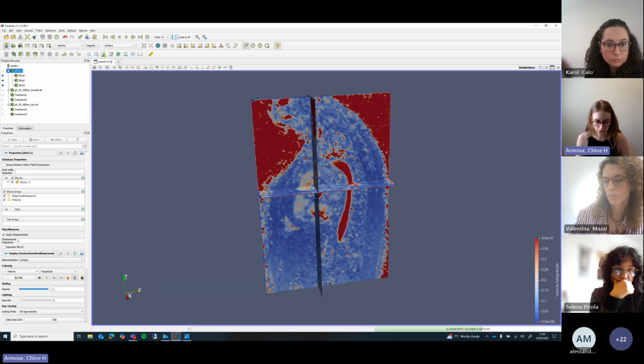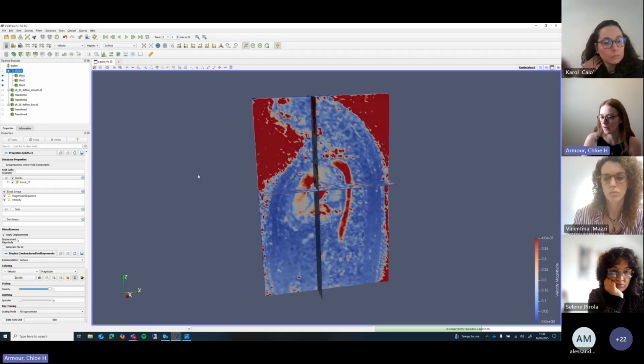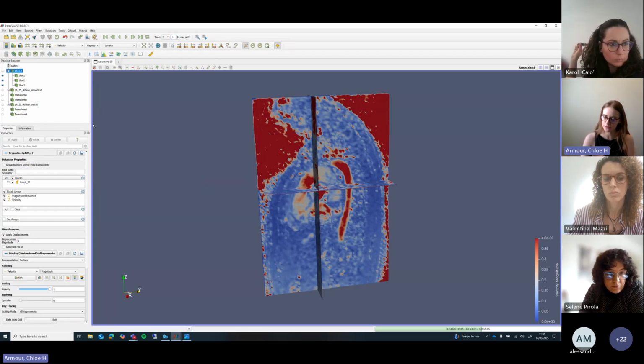25, 30 time points is quite a good resolution. You don't get too much more than that usually, due to the limit of the patient being able to stay in the scanner for that long. So the first thing there is we have our 4D flow data. And then what we want to do is align a segmentation with this so we can build our CFD model.